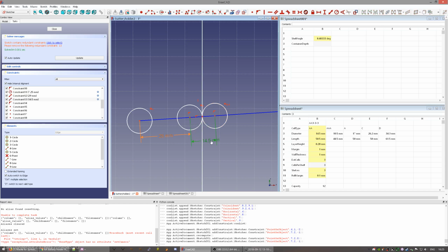As I suspected, it can deduce this because we have specified that these two circles are touching at this point and they have this line going through them, so this point is at the largest distance and this matches their radius. So this constraint is redundant,